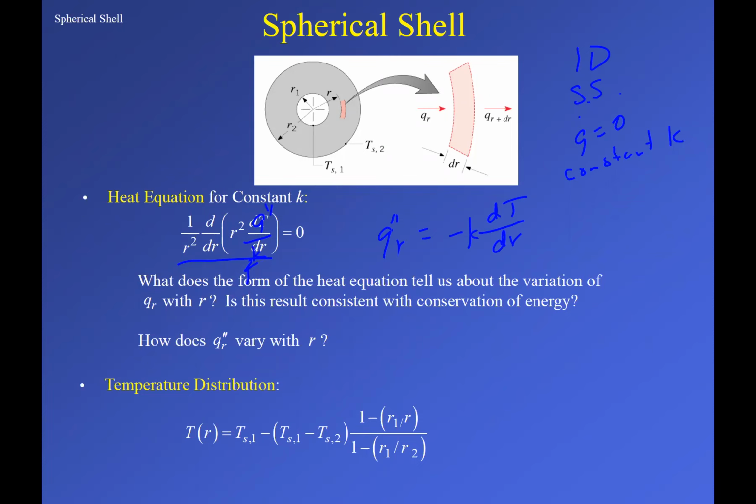So what'll happen is you see it's not constant, the heat flux, right? It's changing with r squared, okay? And that's again because the cross-sectional area changes. See here, you see the surface area that heat would flow if it's going in to out. And then here, that same amount of heat, because conservation of energy tells us that the amount of heat can't change. But the cross-sectional area gets bigger and bigger and bigger, so it changes the heat flux. Okay.